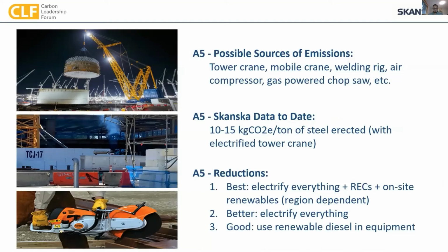It's been really interesting to track this because Skanska has been tracking it on our job sites for a few different projects. We've been able to collect some interesting data and normalize it against how many kilograms of CO2 we are emitting per ton of steel erected. 10 to 15 kilograms is about what we've seen on a handful of projects. Obviously, we just started this process, and we're trying to grow that data set.